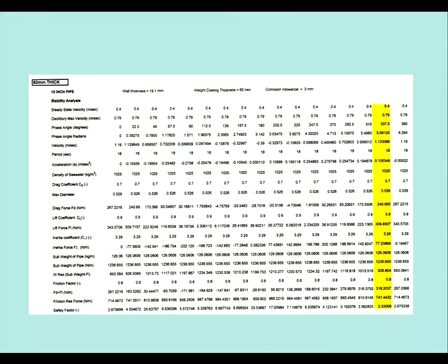So this is what you need to do, is produce yourself a spreadsheet, put all the forces in and step through the different phase angles. As you can see, here's your phase angles, and you step it through from 0 to 360 degrees or 2 pi radians. And then what you've got to look at, across the bottom, where you've got to set the minimum safety factor, which is that fella there, 2.33, that's got to be above the figure that you want. You've set this now. So try to do all that in an exam. It's crazy.